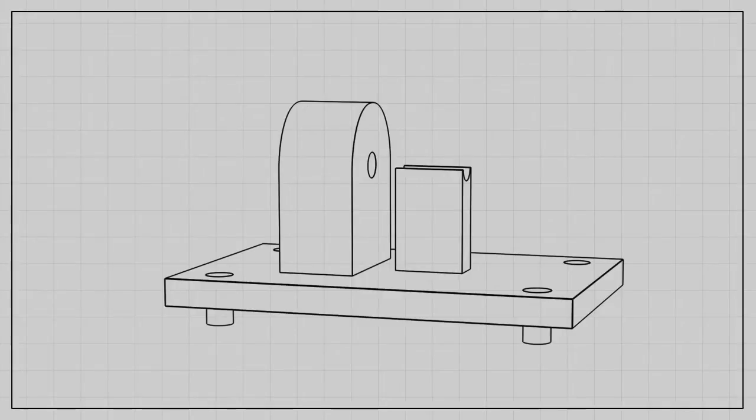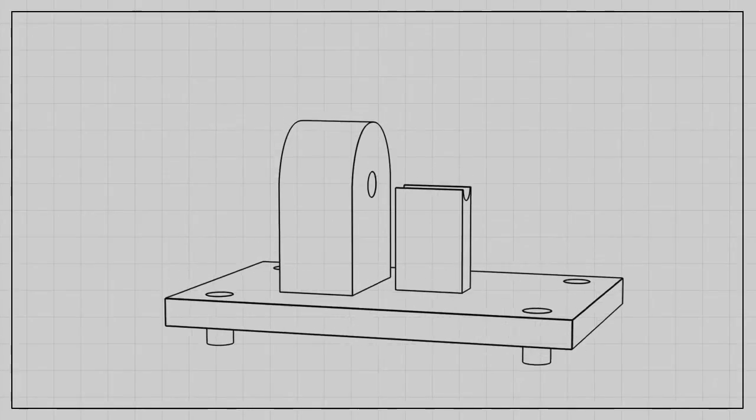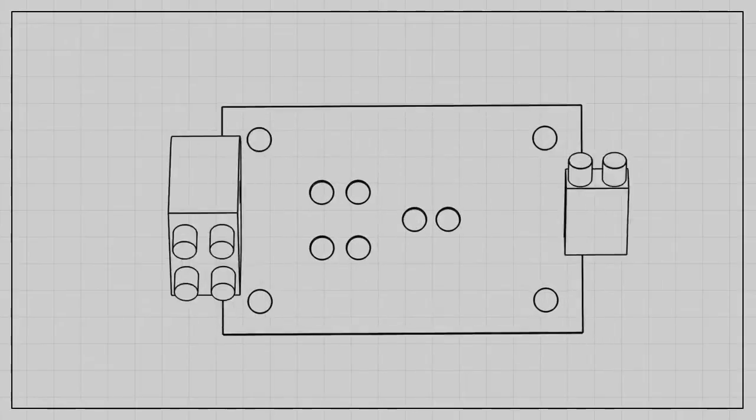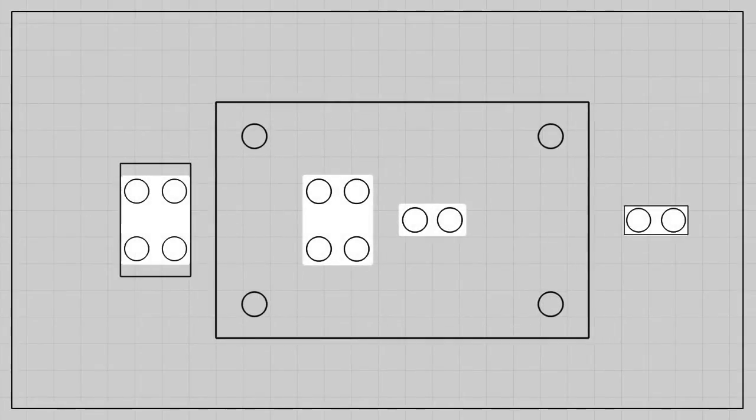By dimensioning to the edge, the designer has put unnecessary requirements on the machinist, which could actually make the part more expensive. The correct way to dimension this part using GD&T is to define the theoretically exact positions of each hole and pattern, then add allowable tolerances to the hole features in relation to each other.